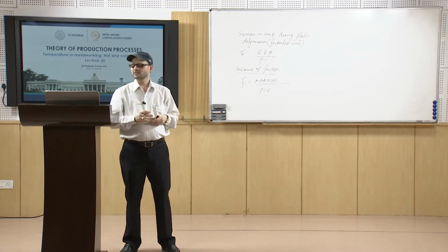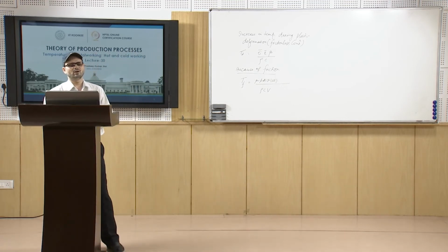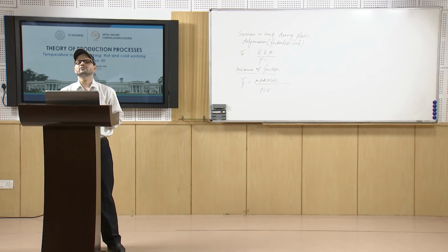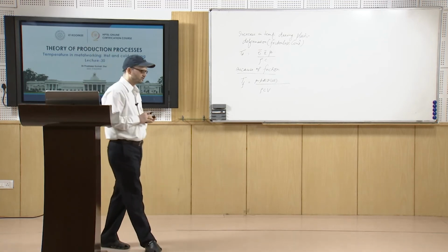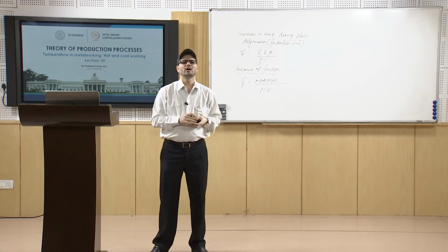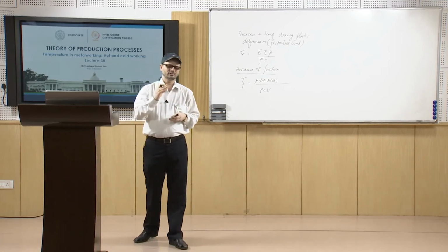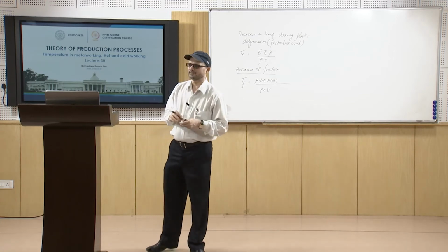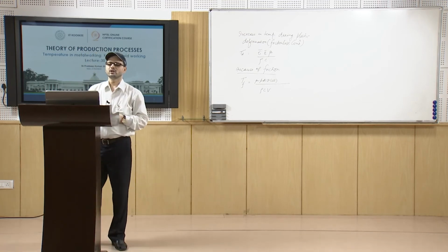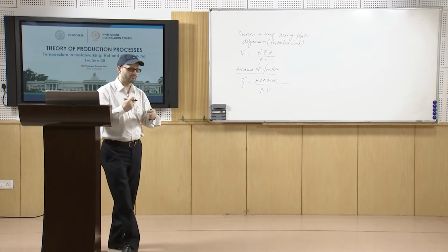These are the challenges that you will have to overcome. Next is surface decarburization. There may be cases of surface decarburization, and in that case you may have to remove certain layers from the top, so that you get an adequate surface of requisite quality. That enhances the operating cost for making the part work satisfactorily for the intended purposes.